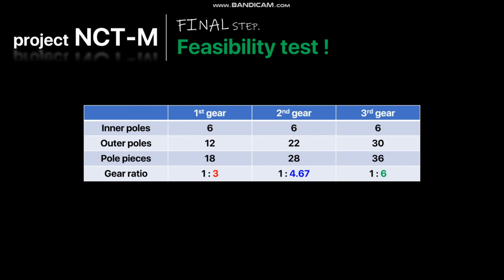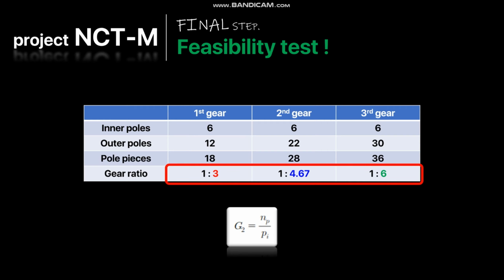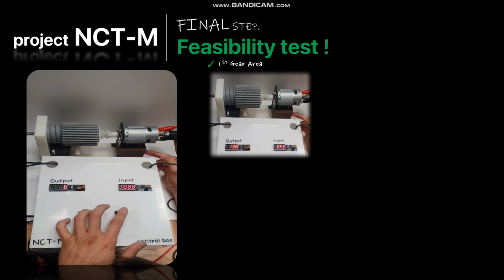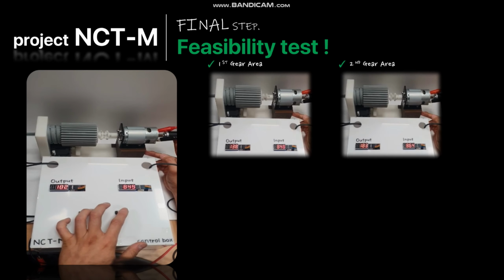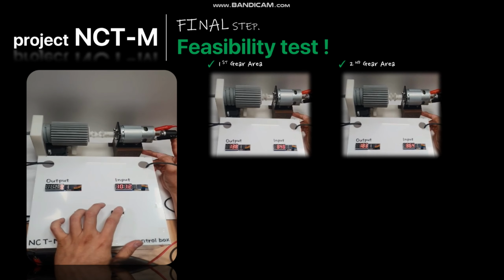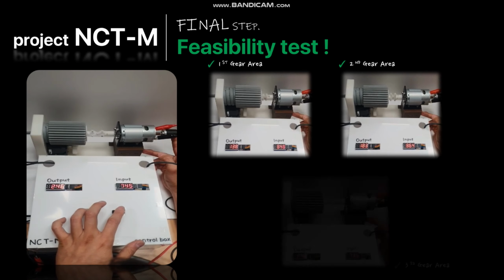This is a table of the magnet numbers we used. We put 6 magnets in the inner rotor, and we put 18, 28, 36 magnets for the first, second, third gear. By this magnetic gear's gear ratio formula, our theoretical gear ratio is this. Okay, let's go back to our operating video. Here's the first gear area, and here's the second gear area. And moving more forward, we can get the third gear area.